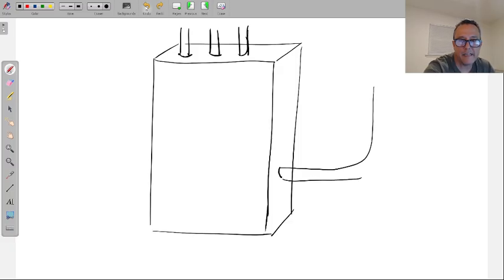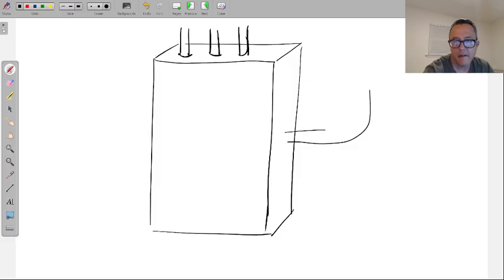But when they turned 90, they didn't get that done so good, and they're going to be a little bit higher. So now they just choose the little hole one above on the panel. But now they've already knocked this one out. So now there's a hole there where there's no conduit in that one, and you're not allowed to turn over a job like that. You're not allowed to say, we're done, walking away, power's on, everything is complete. So they sell these little KO seals, they're called, or knockout seals.